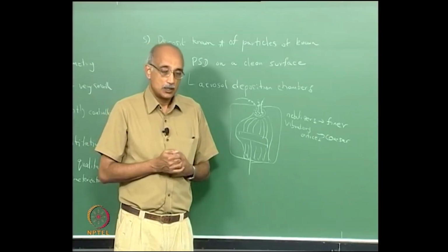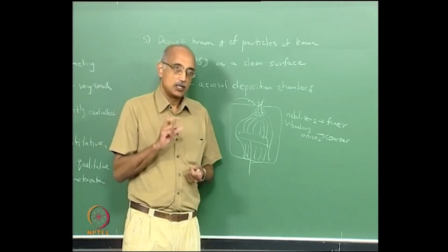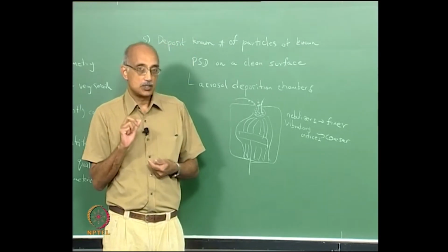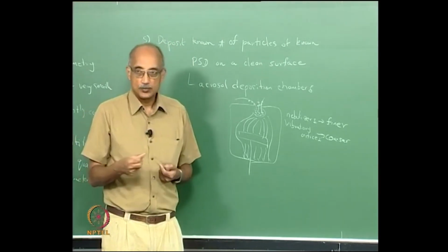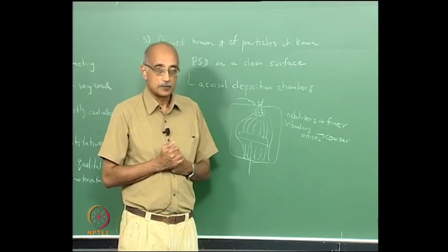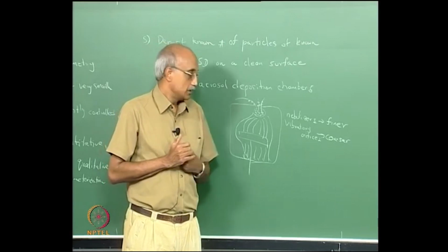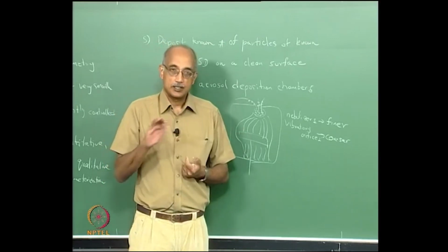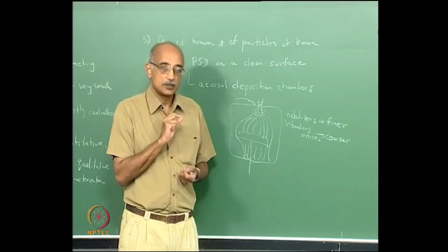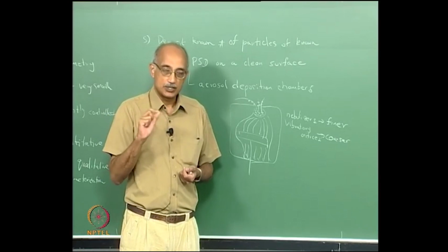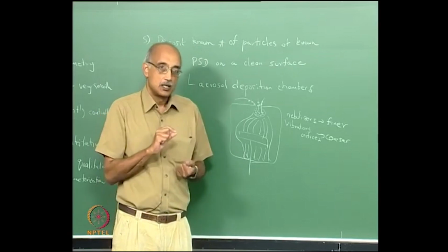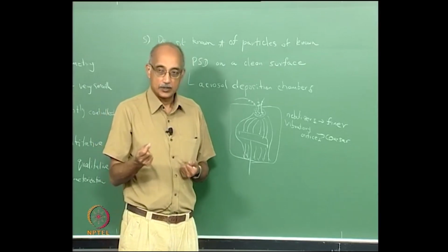For example, when you talk about diffusion, even slight temperature non-uniformities can be sufficient to cause significant thermal diffusion to set in. Similarly, pressure controls are very important. If you are running the deposition chamber at a particular pressure, you have to maintain the pressure as precisely as possible, because even small excursions in pressure can impact both diffusional velocities as well as inertial effects also.